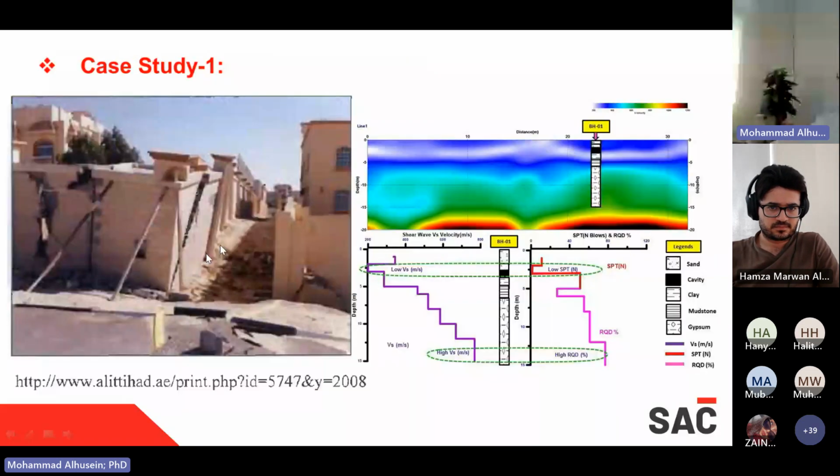See, for example, the case studies, which, as I told you, are the most important things in our presentation today. See, for example, this residential case. Fortunately, some of them, for example those erected on piles, don't have problems. The problems appear only where they have, for example, the slab on grade. The slab on grade inside the building, not a suspended slab, settled even 1 meter or more due to, for example, the dissolution of the subsurface soil.